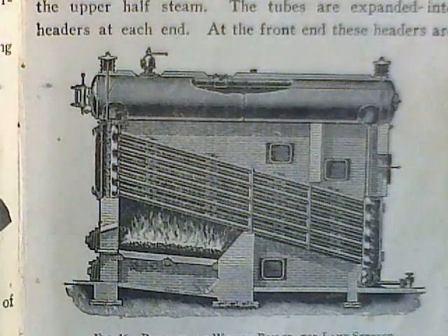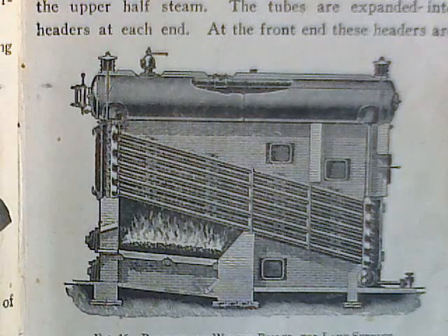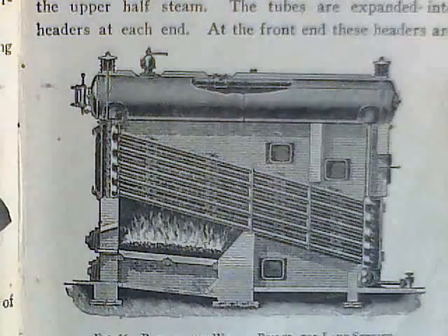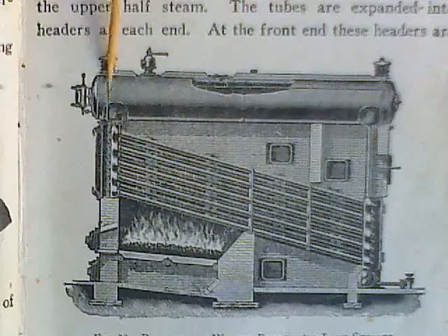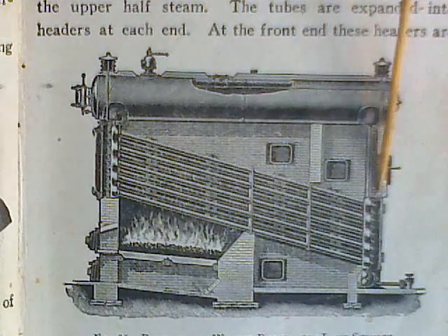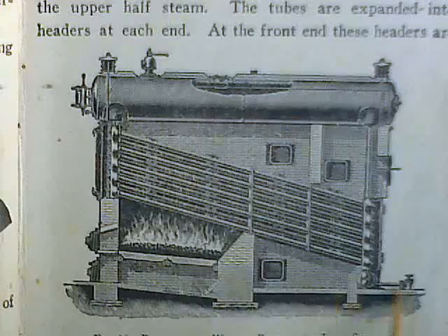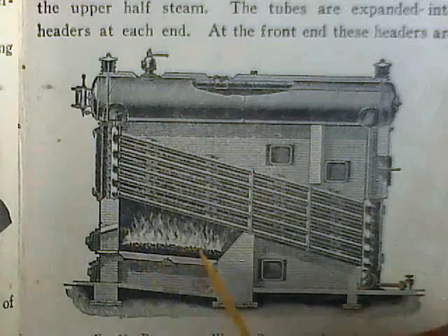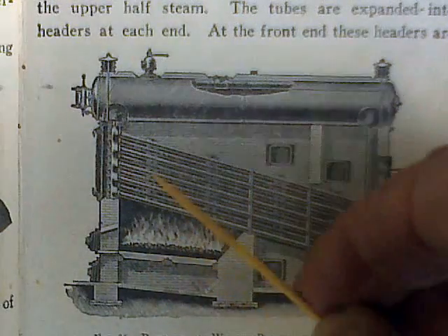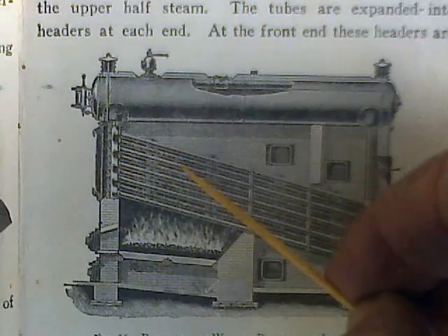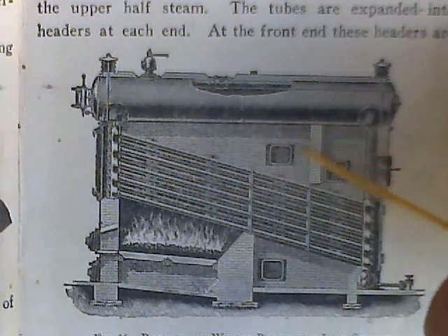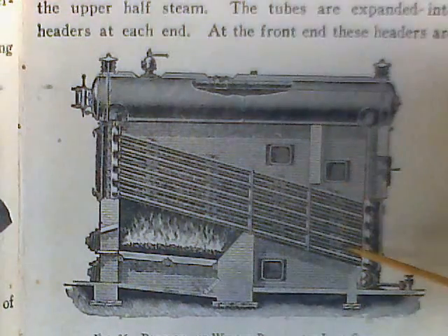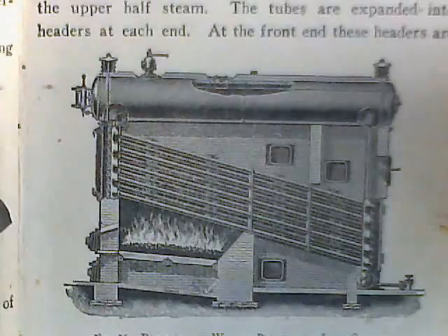What they do is they burn the coal under a boiler. Now, this kind of boiler is what's called a water tube boiler. And the way it works is that this tank up the top here is full of water. The water comes down into a gallery, gets fed into a series of parallel pipes that run up over the firebox. Here's your coal burning in the grate. The fumes from the burning coal, the hot gases, come up running around these water pipes along the bottom of the boiler, down past this baffle wall, down around these water pipes, up past these, and to the flue out here.